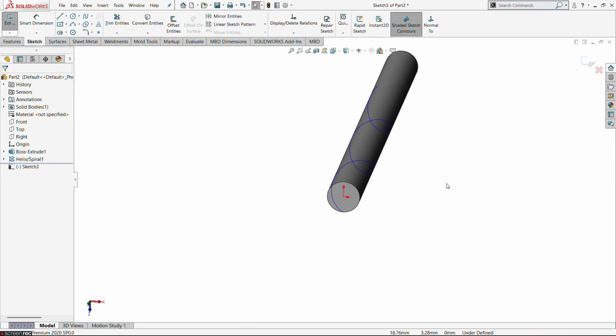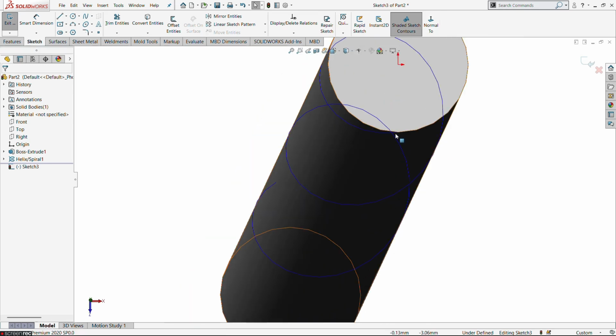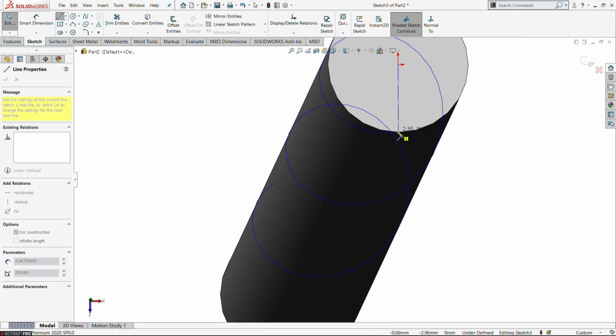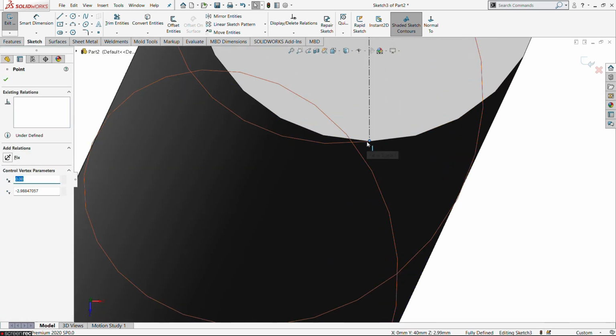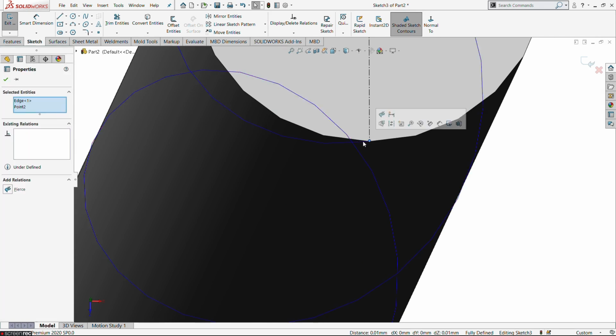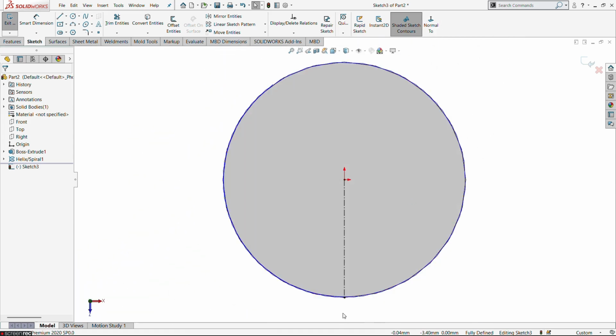Once we create the curve, select these faces and create a new sketch. Let's draw a simple vertical construction line from the center point. So select the center line, and start from its origin point up to its end point. Afterwards, choose this particular point as well as the curve by holding the Ctrl button, then use a Pierce constraint to fix them within each other.